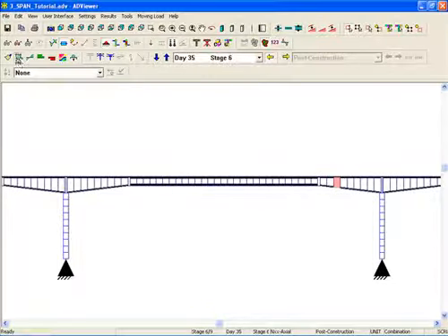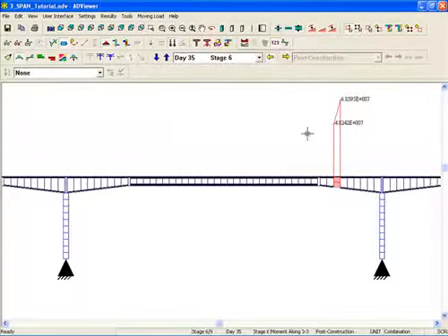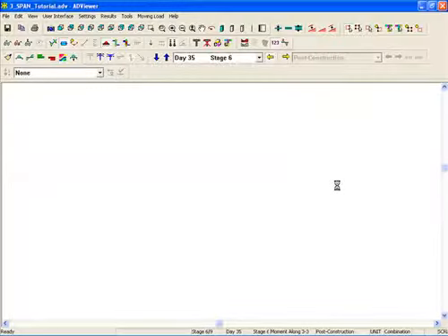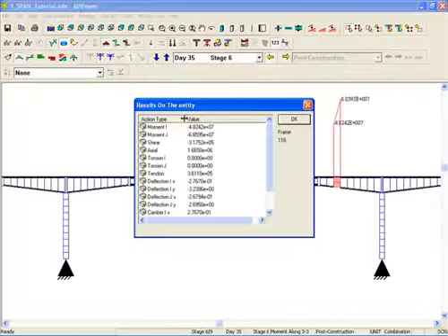We'll select bending moment again. The bending diagram along that element will appear. We can review results. With that moment diagram turned on, we can again select the element, and the results on the entity will appear. This is frame element 116 with the applicable results.